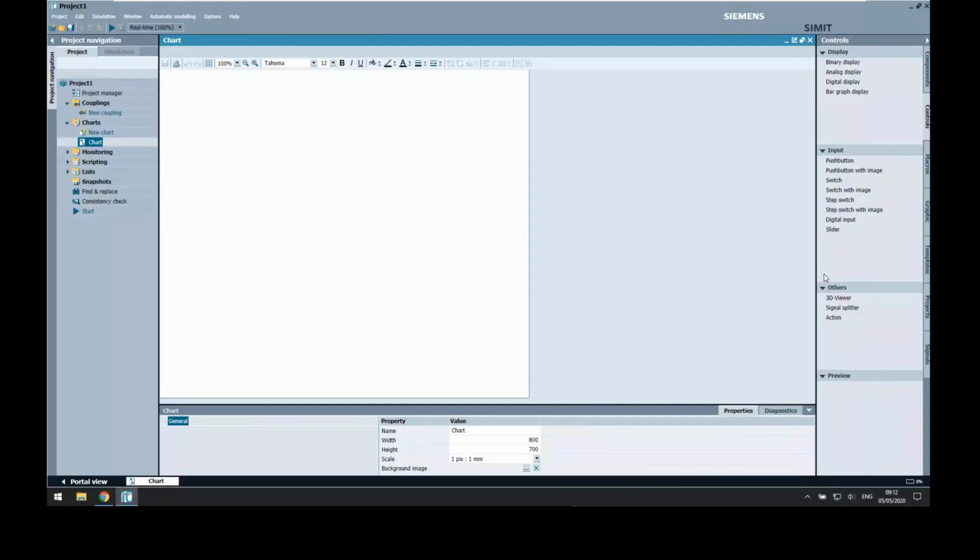But we have the simulation running in PLC SIM Advanced. Great. Our code goes through, then we hit a network where we're actually waiting for some feedback. Well then, do we force this bit to be high? Do we include some extra function blocks to provide this feedback? None of these solutions are really great. I mean, the third thing we could do, we could probably wait for our real system to be built and then evaluate it. But this is just wasting time. This isn't the way of lean development.